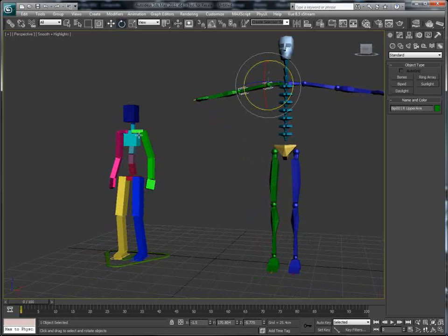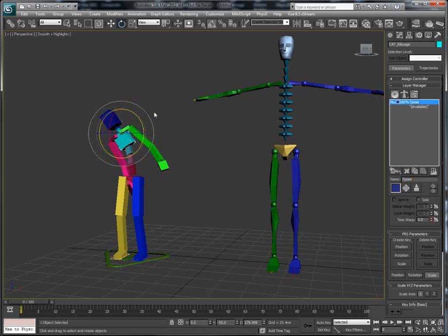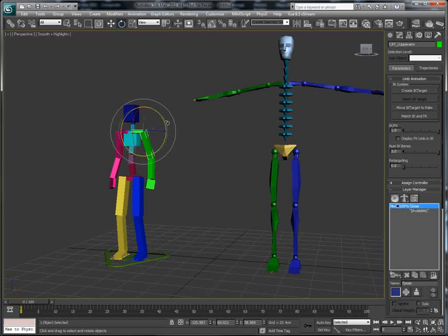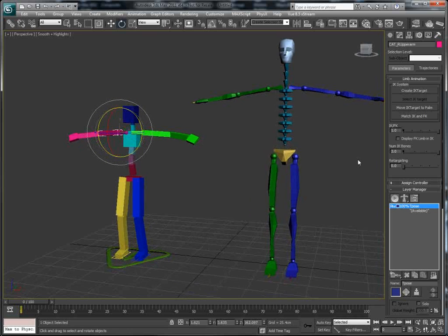Before I rotate on this character, right now he is in setup mode, so I'll create an absolute layer and call that T pose. That's my layer naming, or just where I'm going to save this T pose. I'm going to grab the arm and rotate it again 75 degrees, and this one here as well, 75 degrees, just to make sure they are in a T-stand pose like that.